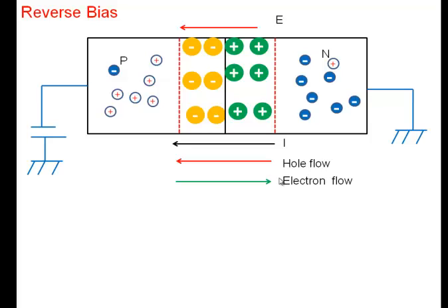Now you can see the trouble. You're asking holes to flow from right to left. Now, is it easy for holes to flow from right to left? Easy or not? Of course it's easy. Why would you say that? The electric field helps here, right? Yeah, concentration is low, but electric field helps, right? So if a hole, let's say, is able to reach this region, then the hole will be simply able to flow. Right? So it's not that the electric field earlier in forward bias was opposing and diffusion was what was pushing it. Now electric field helps in movement of holes from this to this side.